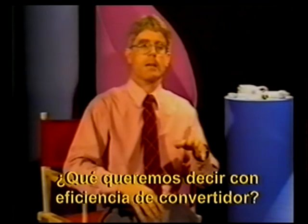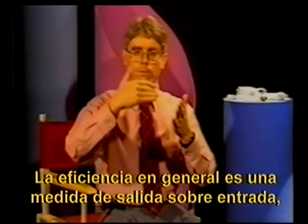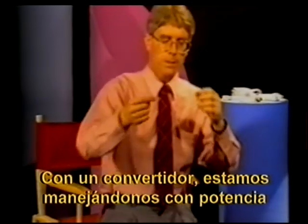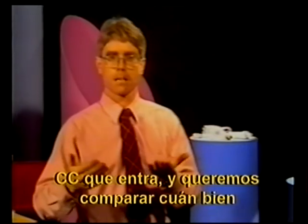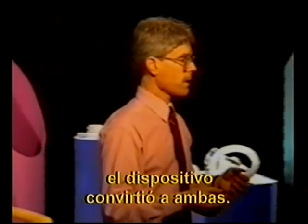What do we mean by inverter efficiency? Well, efficiency in general is a measure of output over input. How much you get out versus how much you had to put in. With an inverter, we're dealing with electrical power out, AC, compared to electrical power in, DC. And we want to compare how well the device converted those two.